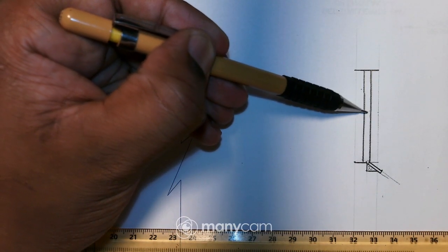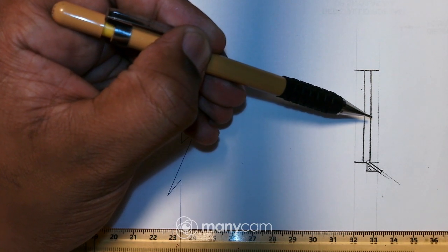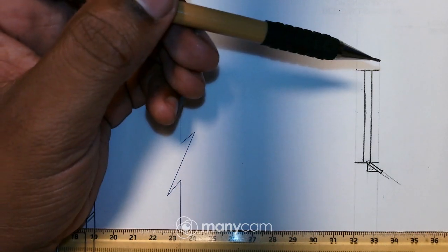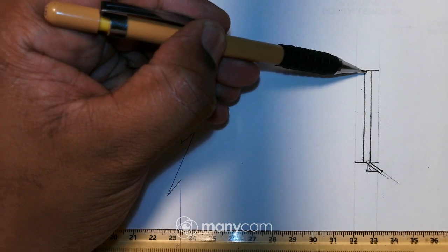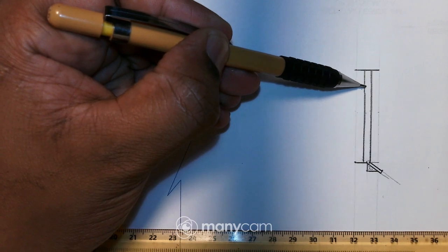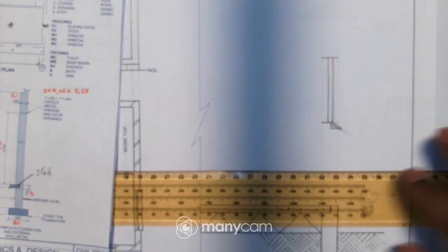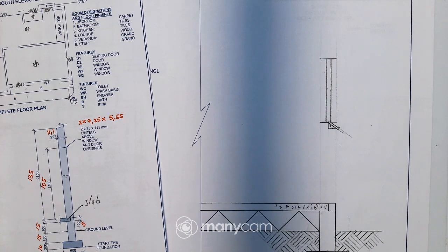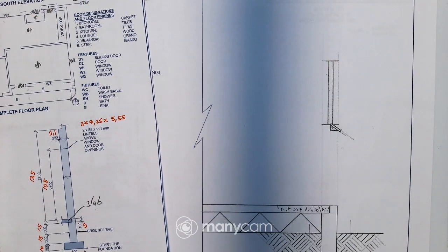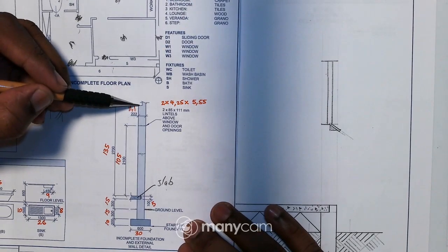So the thickness of the window frame, the standard thickness is 50 millimeters. So if you are given, or maybe you are cutting through the window, and obviously you have to add the window frame, right? So you must know that the thickness is 50 millimeters. Okay, so I'll just proceed with my drawing. So now I have the windowsill and the window frame. So now I have to draw this part now, right?